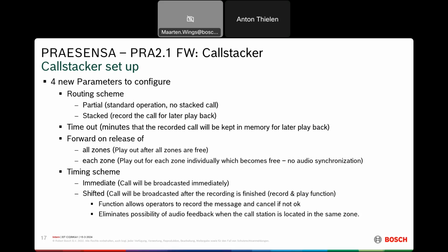So then you can set it to each zone. And then you have your timing scheme, and that can be immediate. That means your call will be broadcasted immediately to the available zones. You could also have a shifted call, which will be broadcast after the recording is finished. That's a record and play function. This last one allows operators to record the message and cancel it if not wanted, and it eliminates the possibility of audio feedback. So those are the settings which are now added.